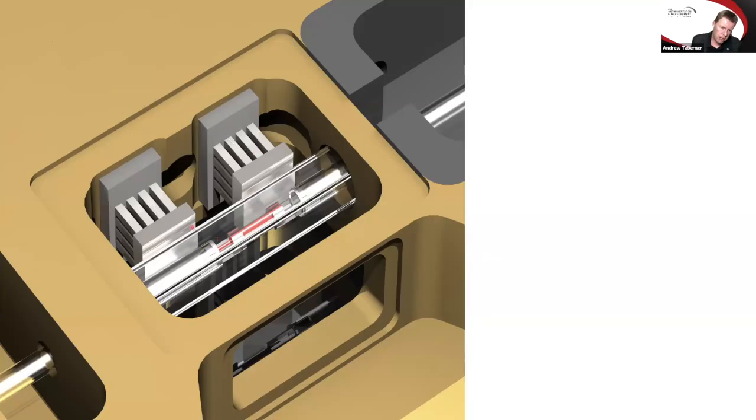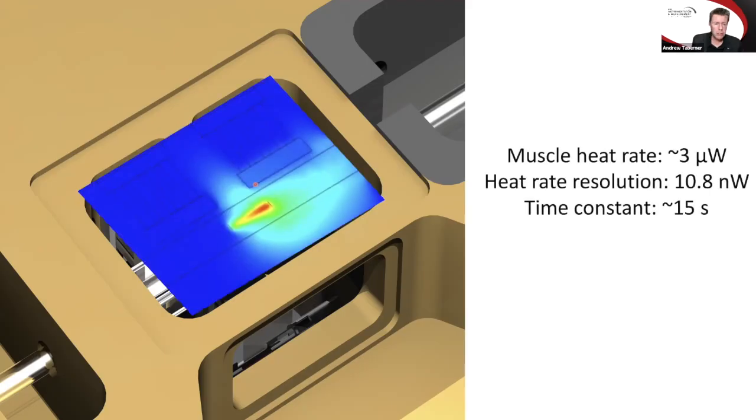So we have two thermopile sensors that we have put, one upstream of the muscle and the other downstream. So we wash the muscle with solution. As that solution passes along the length of the muscle, it is increased in temperature, and our two thermopile sensors, which are actually just very small thermoelectric heat pumps used in reverse, measure the temperature increase of that solution to around about 1 millikelvin temperature change and about 1 to 2 microkelvin of resolution. So it's an extraordinarily sensitive measurement to make.